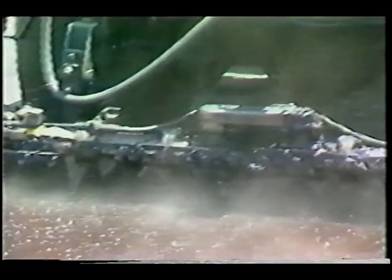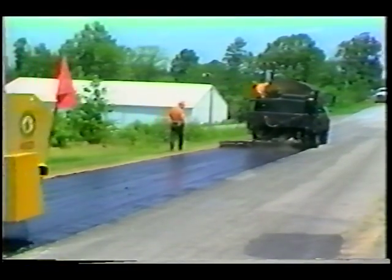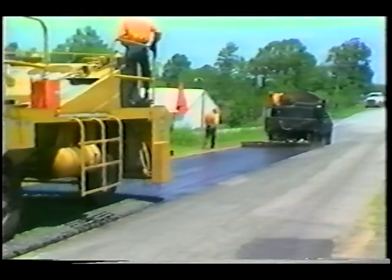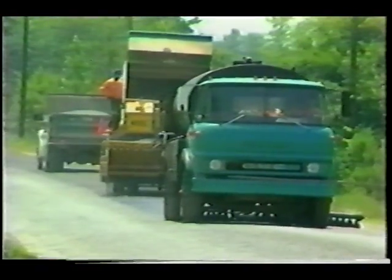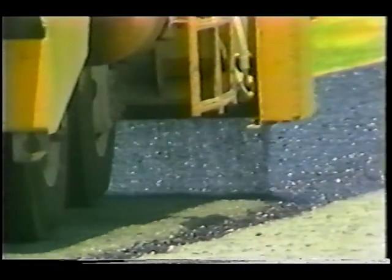Asphalt chip seals can be single or multiple layers. A single layer asphalt chip seal consists of a sprayed application of asphalt covered with a layer of aggregate of a uniform size. A multiple surface treatment consists of repeating the process with the aggregate size becoming smaller with each application.